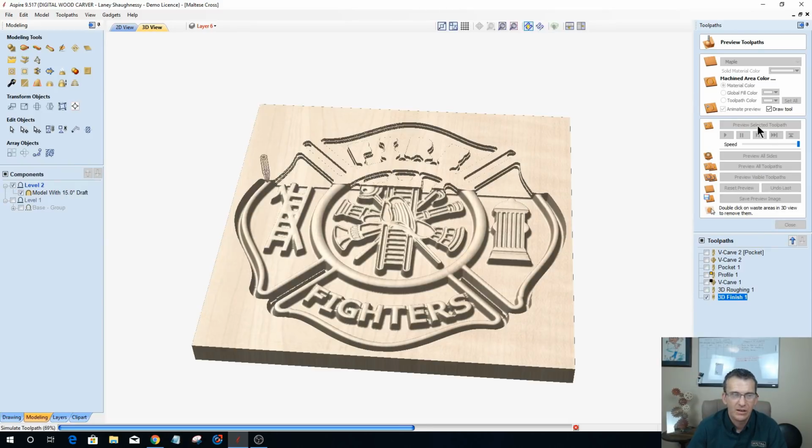If you need to get down, like in this case, a 1/16 inch tapered ball nose versus a 1/8 inch tapered ball nose, to get a little bit cleaner around those letters and all. Even possibly a 32nd, right? A smaller one, but it creates a long carve. And so you would just use the one bit for your finish cut. Desktop and Pro users. Aspire users have a technique that is called rest machining that they can use.